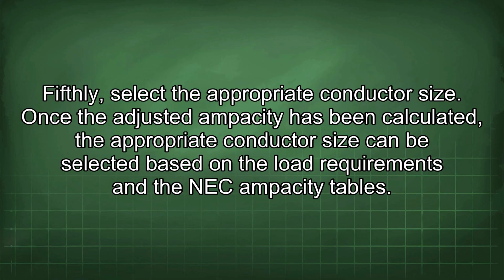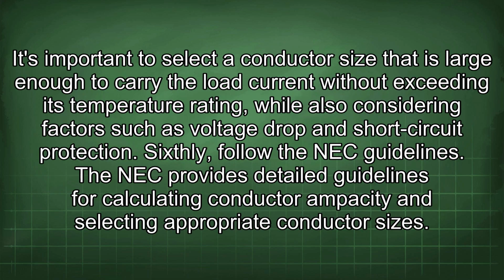Fifthly, select the appropriate conductor size. Once the adjusted ampacity has been calculated, the appropriate conductor size can be selected based on the load requirements and the NEC ampacity tables. It's important to select a conductor size that is large enough to carry the load current without exceeding its temperature rating, while also considering factors such as voltage drop and short circuit protection.